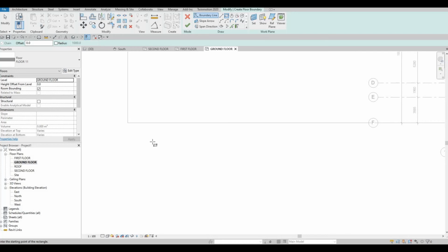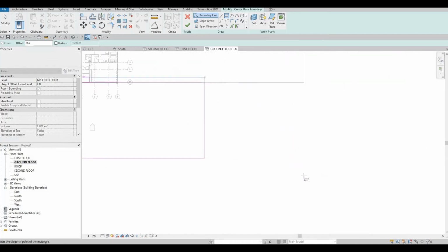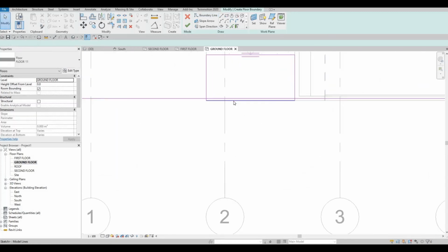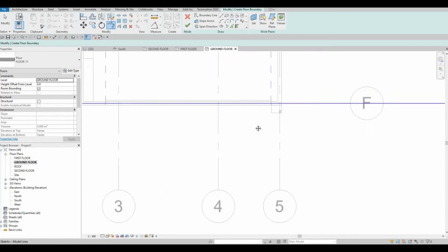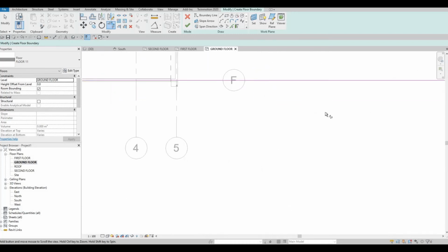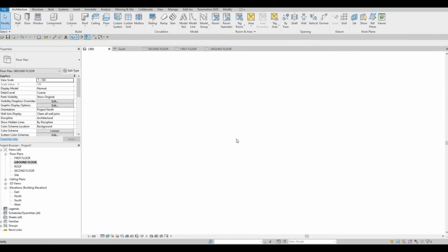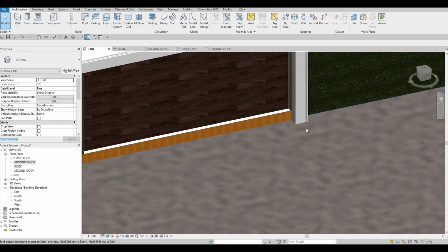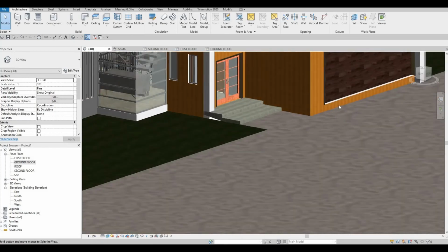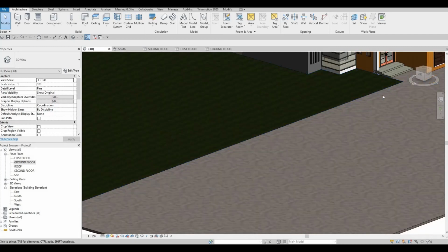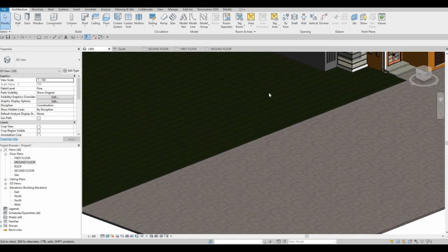But we're not yet done. We need the concrete for our street. So now we could just delete this SL. Let's split element, TR, trim and extend. Once you're done, click finish, and let's look at it at 3D. Okay, that looks okay. Let's add in our side street, sidewalk.